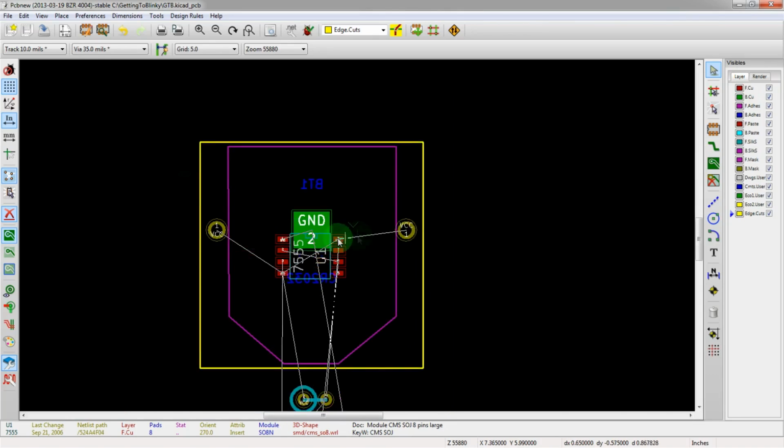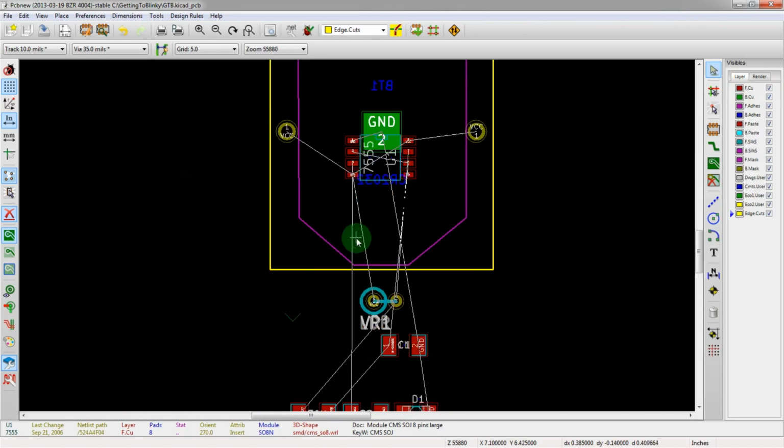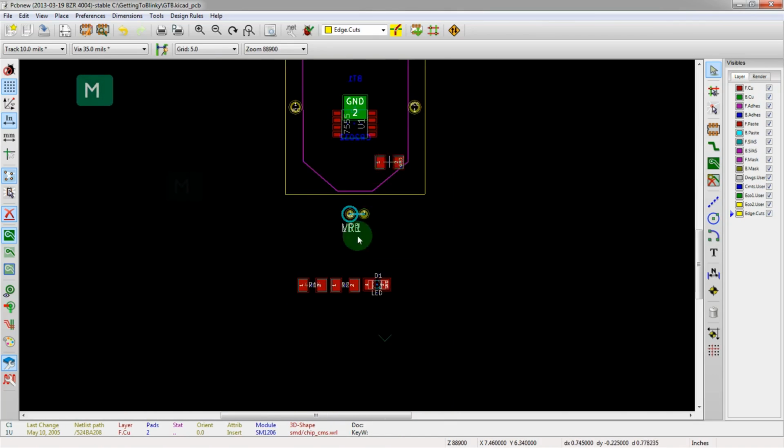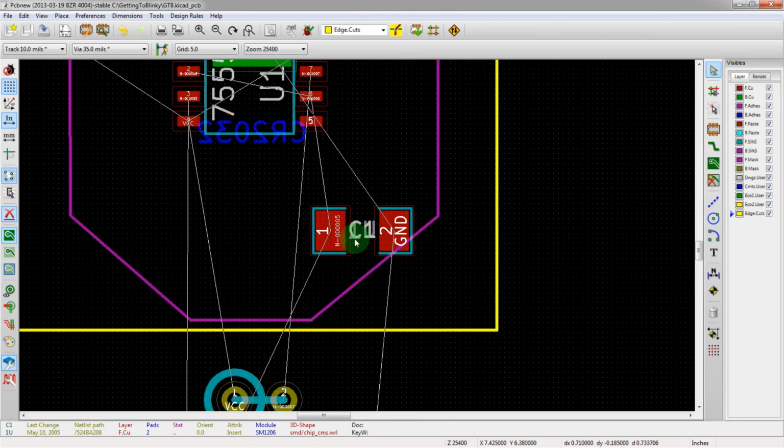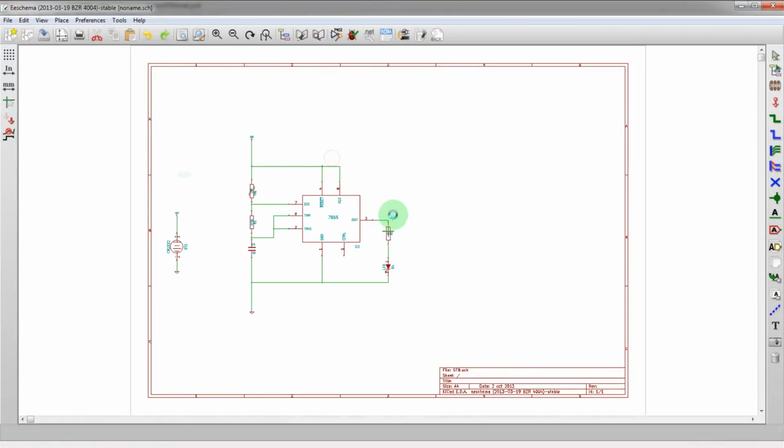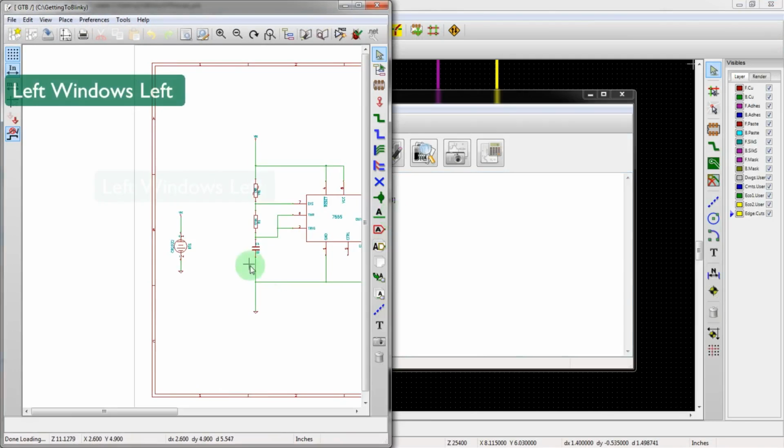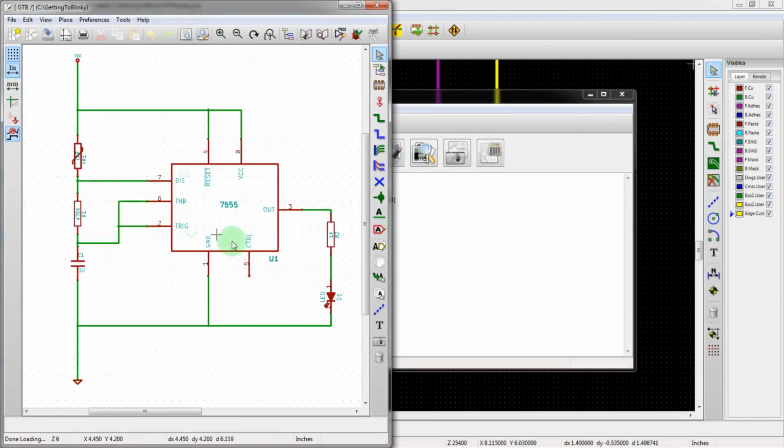All right, let's go ahead and move the rest of these components. Now, I'm going to start dragging these around, and we'll actually be able to see some of the connectivity. We might also want to split screen this with the schematic, because looking at the connections as you're going along can really help to figure out what should be connected to what. So let's keep it like that.